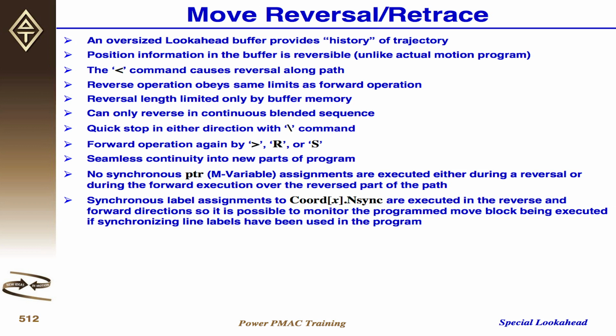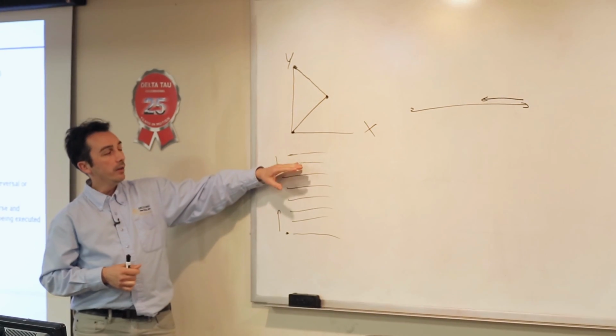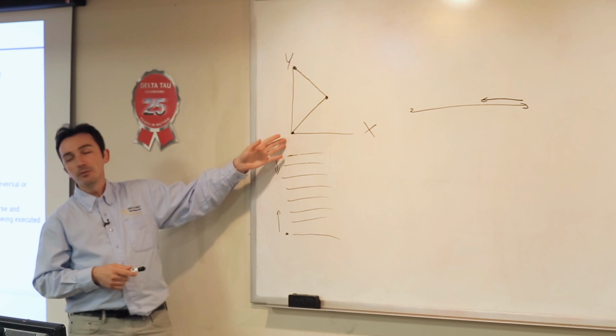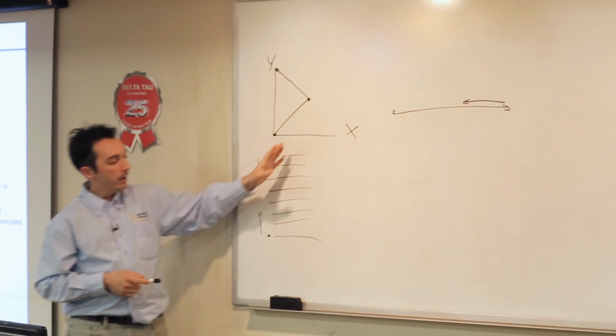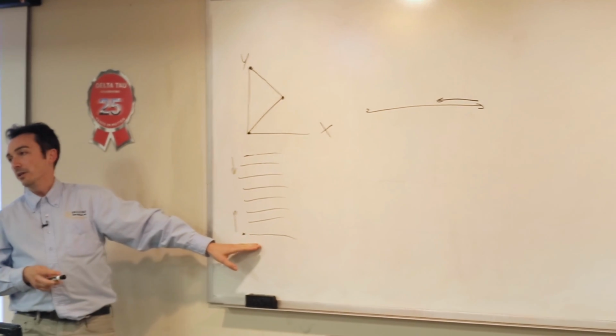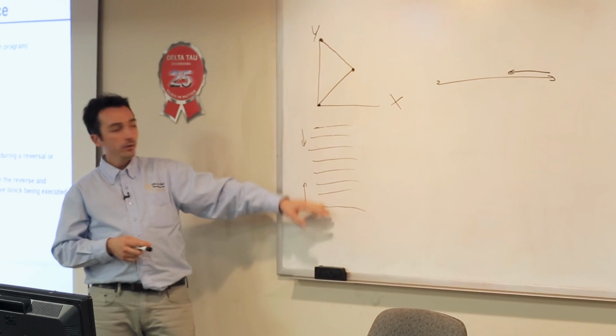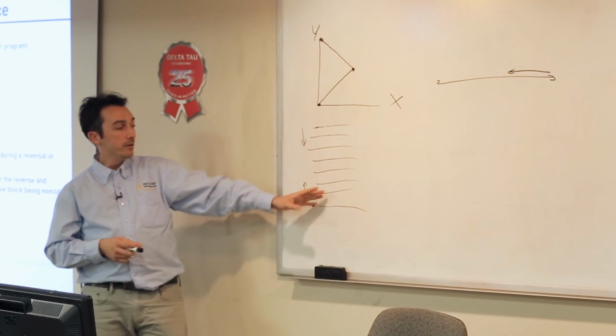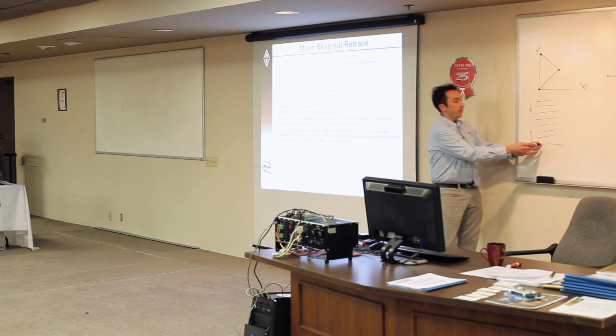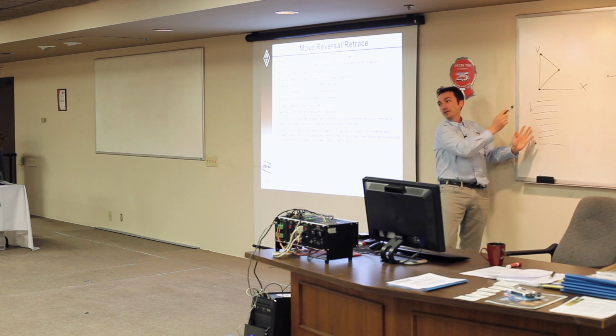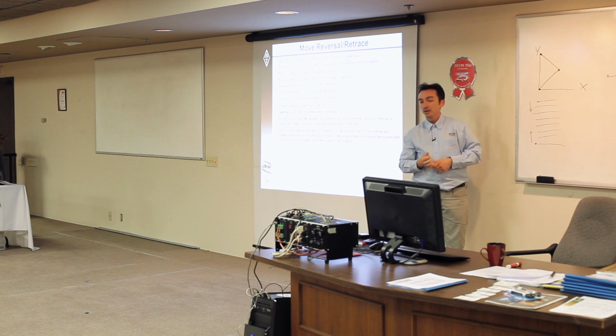Remember, in a motion program, it's getting executed line by line. So you start from open program 1, and then until the end, the close, it's executed line by line. There is no way, before the close, that you can go back in the opposite direction.